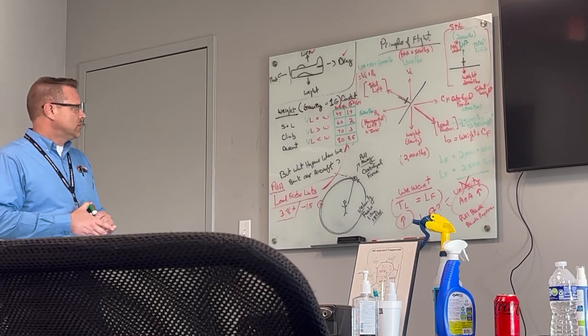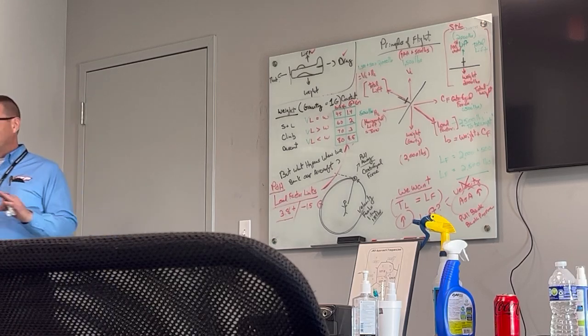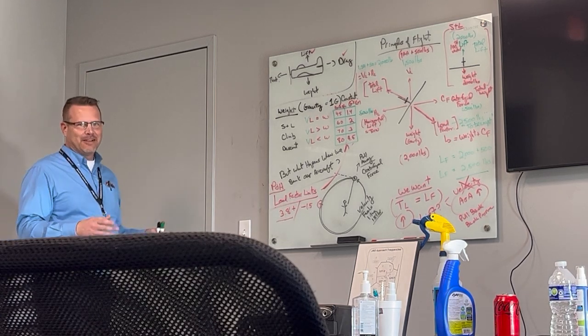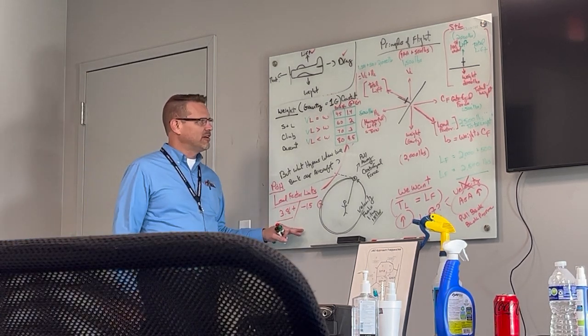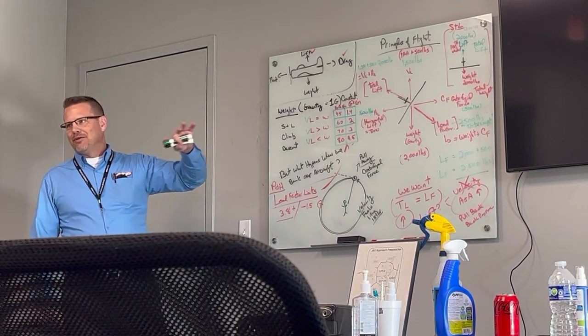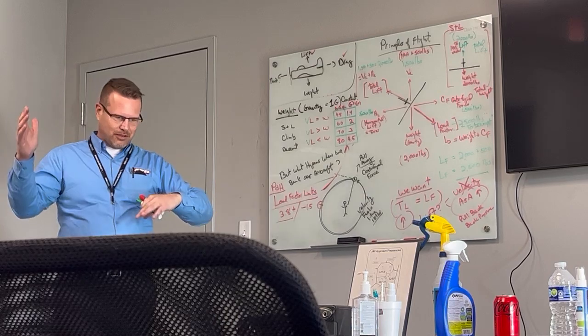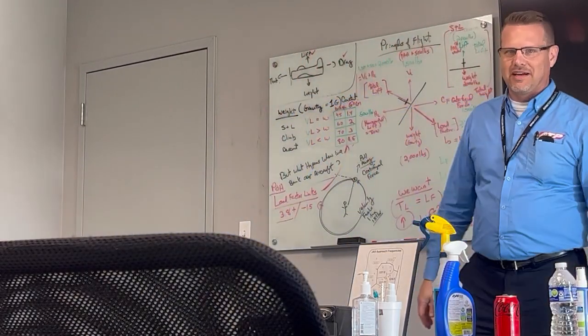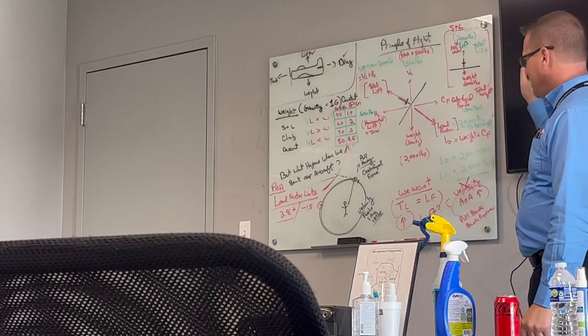So this is typically where I leave it. I don't really go much further than this, and some people say, well, you can't do this and not do VA. I have some people who are real gamers, and they want to do VA, and I'm like, fine, throw VA in there. You know what I mean? Make your lesson a little extra special, because from here, you can explain why, when you're heavier, you're closer to the critical angle of attack, and it will stall sooner, all that kind of stuff. You get into that in the VA chart and everything.